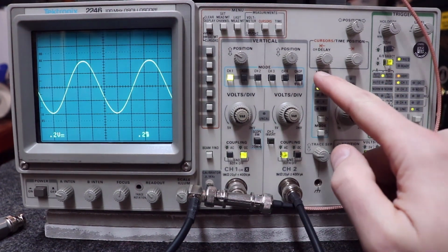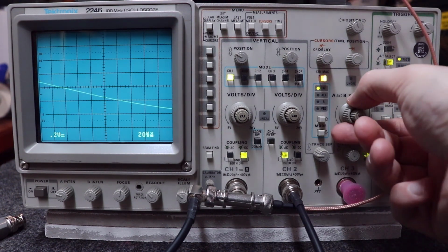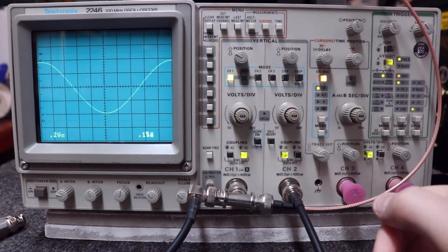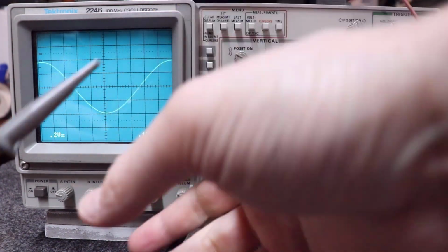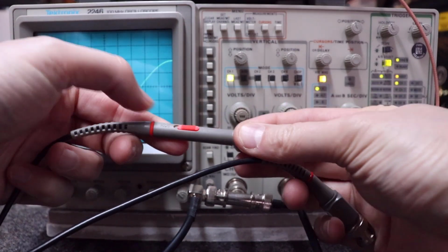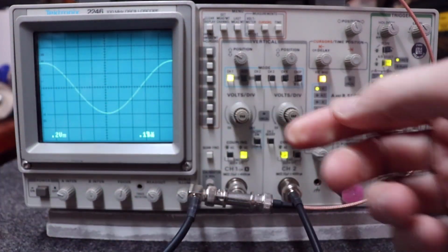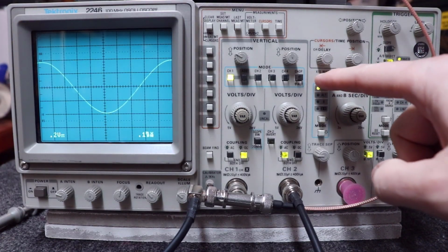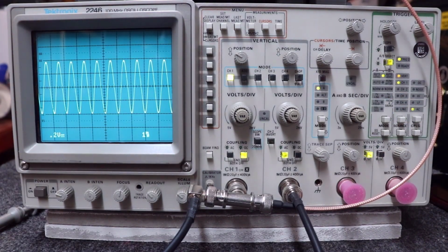You've got something here called 10x magnification if you want. You can zoom in on that thing. It gives you 10x going this way. Now, 10x going horizontally, you typically pick that up via a little switch on your probe here to go from 1x to 10x. But if you want to go 10x on this axis, it actually gives you a button here on the oscilloscope to give you a 10x function back and forth.